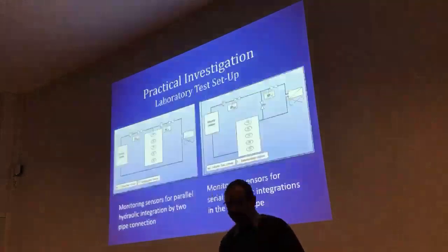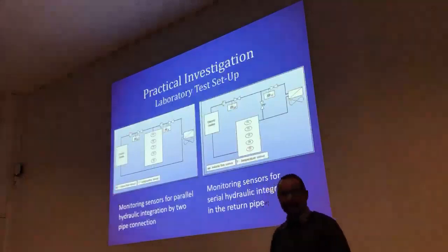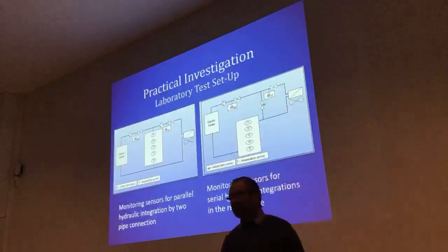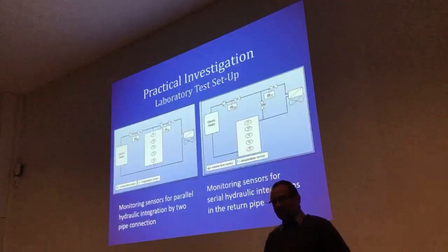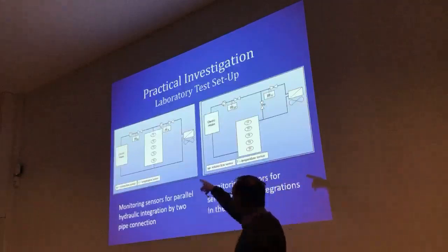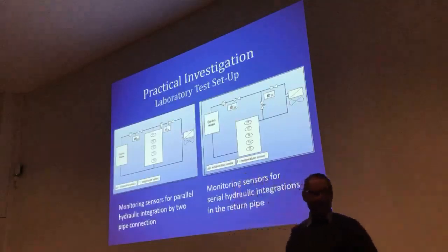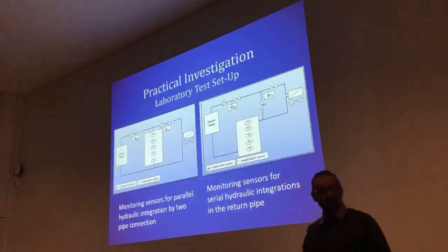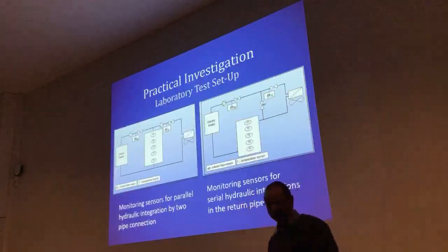In this test facility, the heat pump was simulated by an electric heater, which was able to give a heating capacity from 3 up to 19 kilowatt. That electric heater was able to operate in a constant temperature mode, that means the outlet temperature was constant, or under constant power mode, that means if the inlet temperature rises, also the outlet temperature rises.